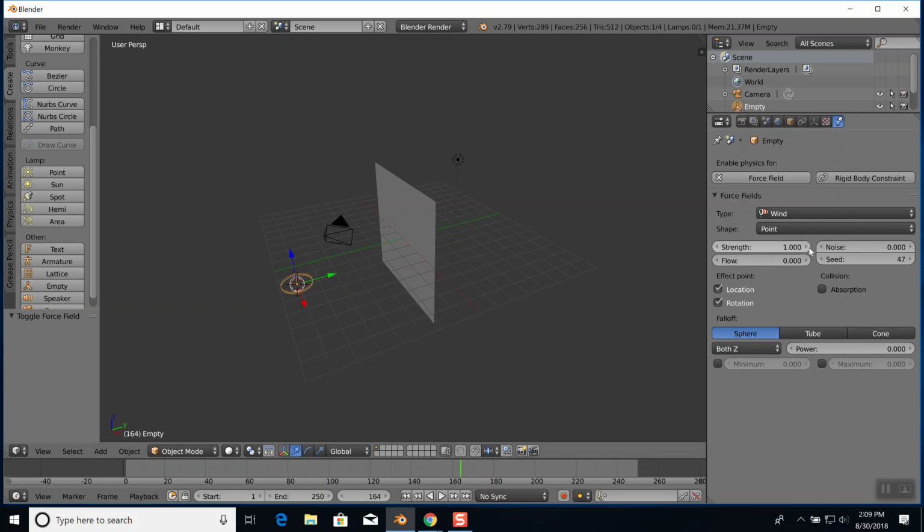Now the strength is 1. If I start increasing the strength, keep clicking it, you notice what it's doing? It's going up, isn't it? That went up by 5. Earlier, when I was testing it, I had forgotten what the number should be. I put 1,000 in there, and I couldn't see it at all. And then when I ran the animation, my cloth blew off the screen. I hadn't pinned it, and I'm sitting there thinking, well, that's strange, I've not even seen my wind. Again, understanding what that is helps you know what this should be. Maybe 15 is appropriate.